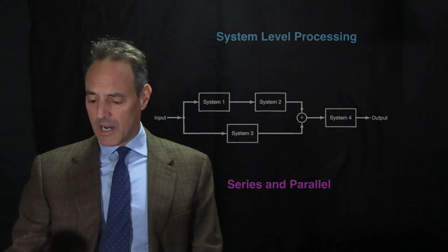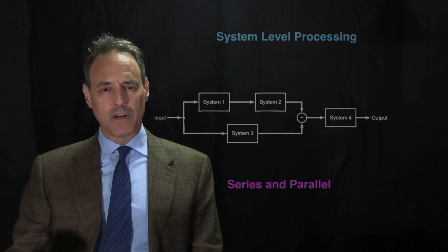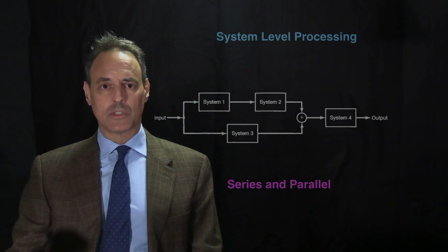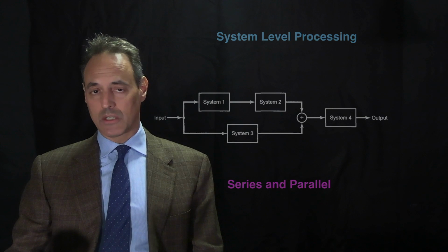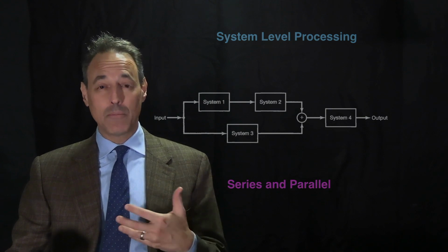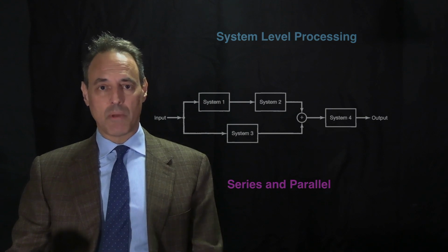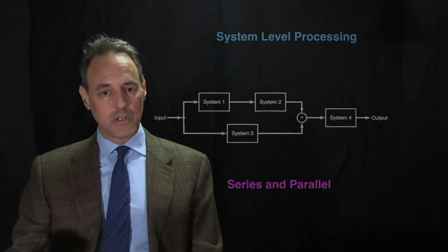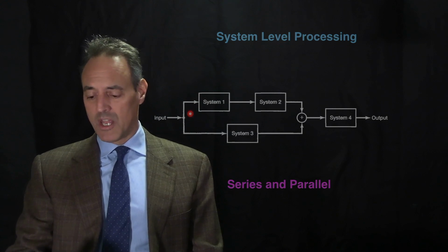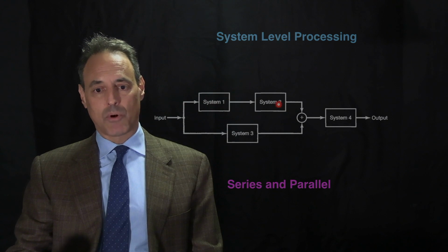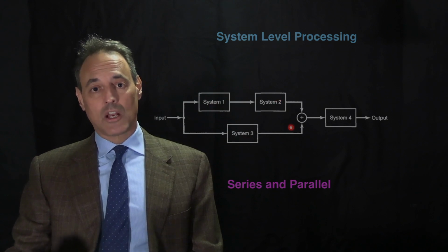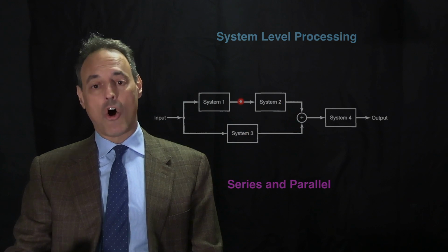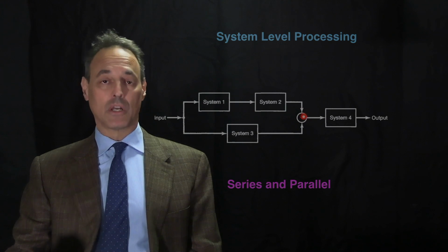Interestingly enough, one of the things that we talked about in the very first lectures was what are the basic things you can do to signals. For instance, time shifting of signals is one of the basic operations. And that becomes very necessary here because maybe there is some time it takes to process the signals, and maybe this path is much faster. So when you combine them, you have to delay this signal so that all these get synced back up when you recombine here.